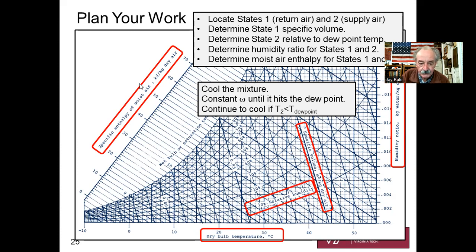So convenient, because look at this diagonal axis on the psychrometric chart, specific enthalpy of moist air. The nice thing about this scale is that it jumbles in enthalpy for the air and vapor mixtures, making it much, much easier to deal with. So be aware of that. And then here, the x-axis, the dry bulb temperature. That's the given temperature measured with a thermometer.